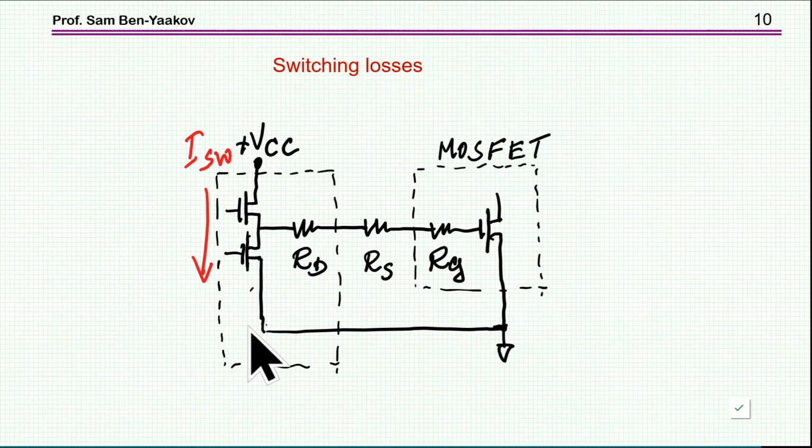But there is another issue here that we have not taken into account, and that is the fact that these transistors are switching, and therefore there are switching losses. Actually, there are a number of types of losses here. First of all, if this is an IC driver, then there is some bias current, quiescent current, that you need for the unit. And then there are some losses during the rise time and fall time, and maybe some shoot through. So this is kind of a mystery here, and in fact, as we'll see in a minute, there is no data about that. Unfortunately, the datasheet does not give us enough information for this, and if you're really worried about it, then you'll have to test the unit itself in hardware, because we don't have enough information.